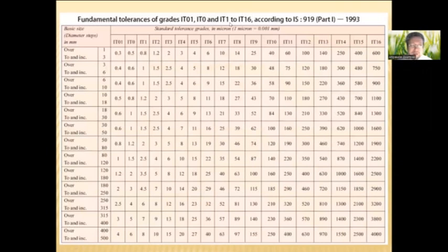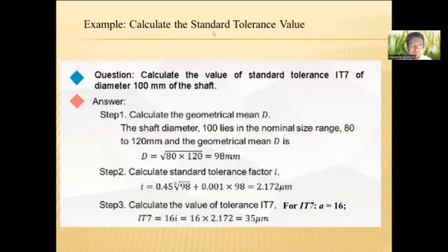There is a table, fundamental tolerances for grades from IT01 to IT16. For example, calculate the standard tolerance value. Question: calculate the value of standard tolerance IT grade 7 of diameter 100 millimeters of the shaft.